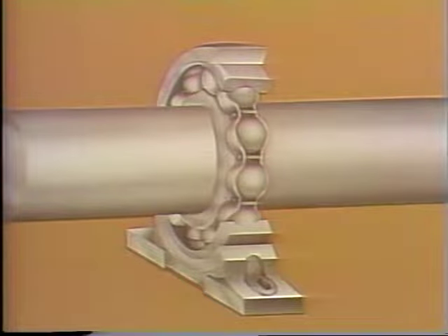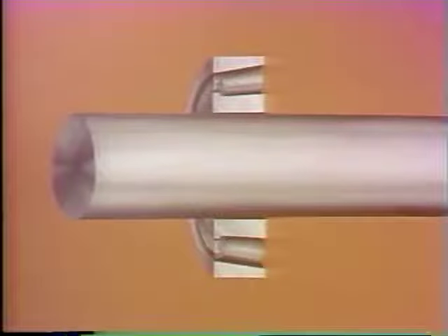In this bearing, the inner ring is attached to a shaft. The inner ring and the shaft rotate together while the outer ring remains stationary. The arrangement of the rolling elements between two rings maintains equal distance between the rings and prevents radial movement. Now, here's a cross-section of another type of rolling contact bearing called a tapered rolling bearing. It can handle both radial and axial movement.